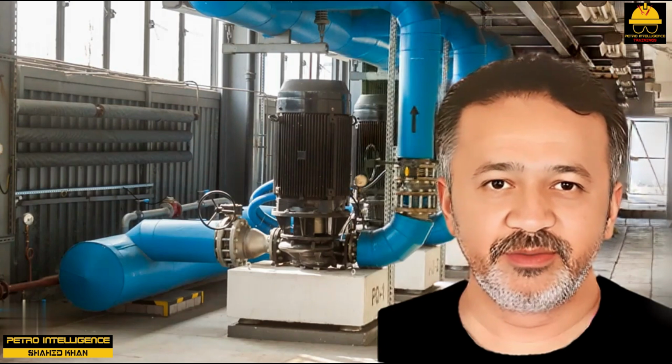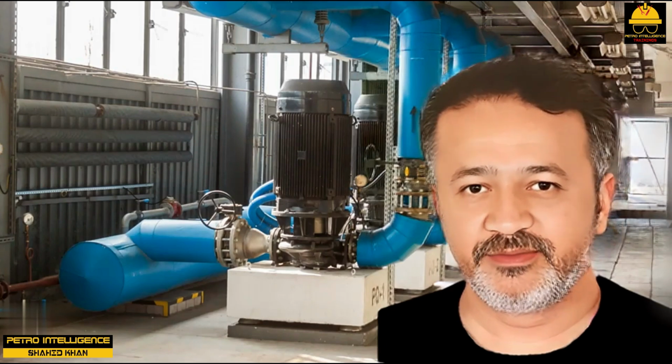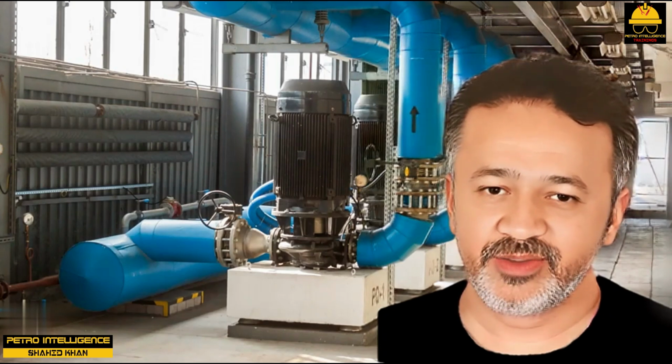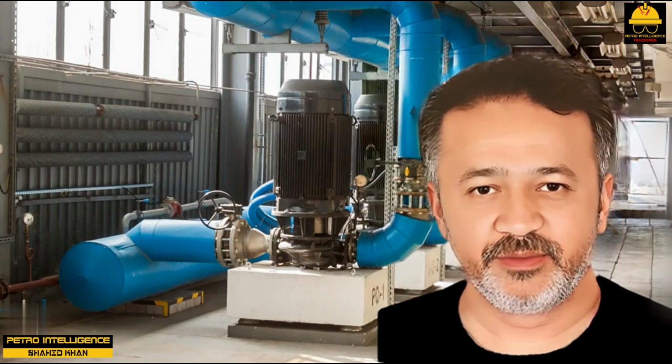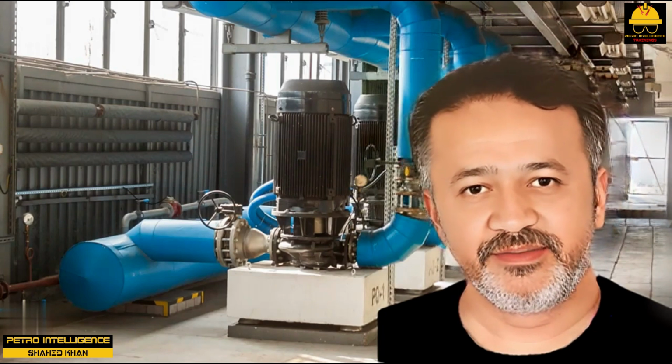Installing a larger impeller may require an upgrade in the pump bearings and the mechanical seal. While it is good practice to purchase a pump with a seal and bearings rated for the maximum impeller size, some pumps can have bearings and seals rated only for their purchased impeller size.